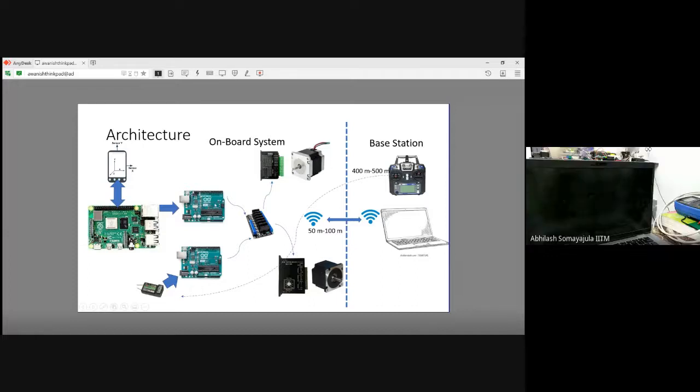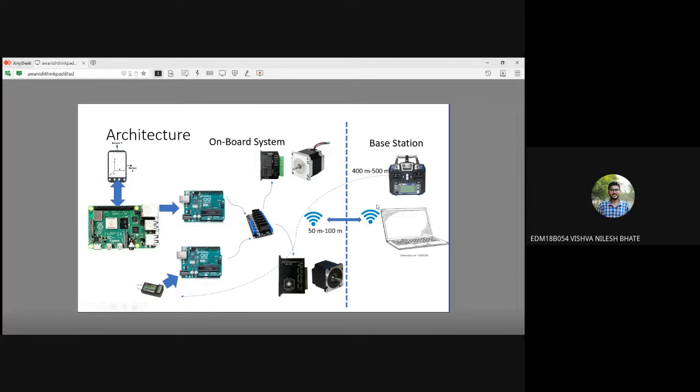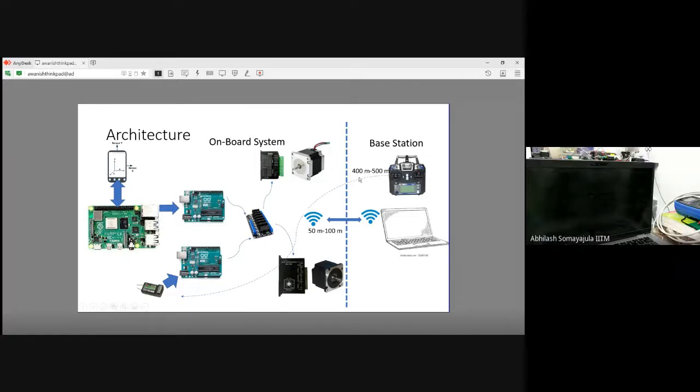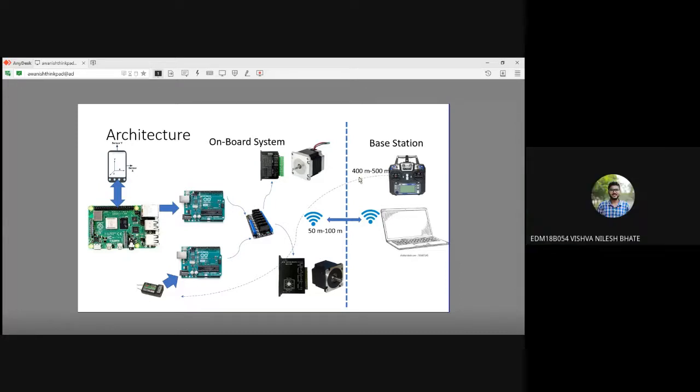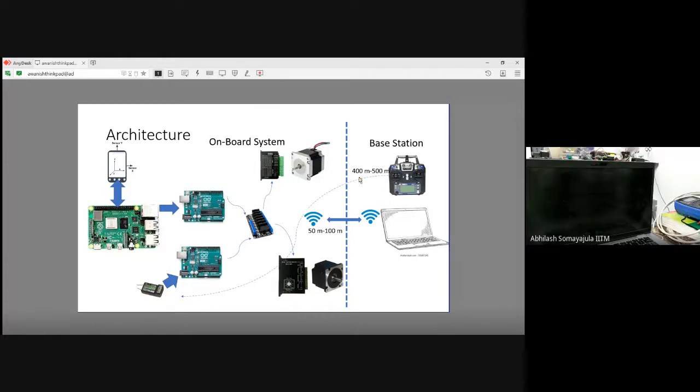So what we are doing is just switching the control signal of this stepper and BLDC using this relay. Relay, okay, got it, and this relay is switched on. But as you said, if the other guy is not doing it, I don't know why it is important, but even if it is important, we can do that because we have one channel which is just switching the relay, and we get some low level or high level logic by switching it.